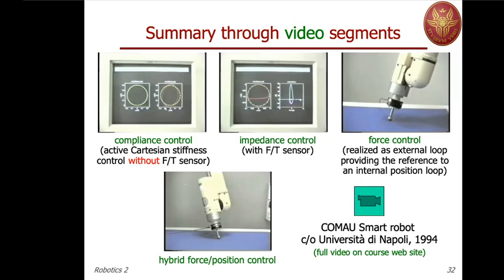If we push before the force torque sensor, the robot is position controlled and will not move because it doesn't sense any force. If we push instead beyond the force torque sensor and we set as regulating force a zero value, then the robot will follow the hand of the human that pulls or pushes the tip. So it's the joystick characteristic that we have seen before.